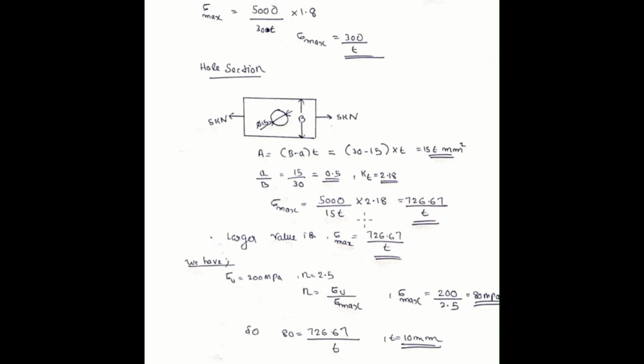We should always take the maximum condition because we are designing a shaft. We have to take the maximum possible thing that can happen to a shaft or whatever material, because it should be fail proof, right? This is a matter of safety. So we need to consider the maximum stress. Okay, so the maximum stress is developed due to the hole, so we need to concentrate on that value and design the material based on that stress, because the smaller value will come under that, right?